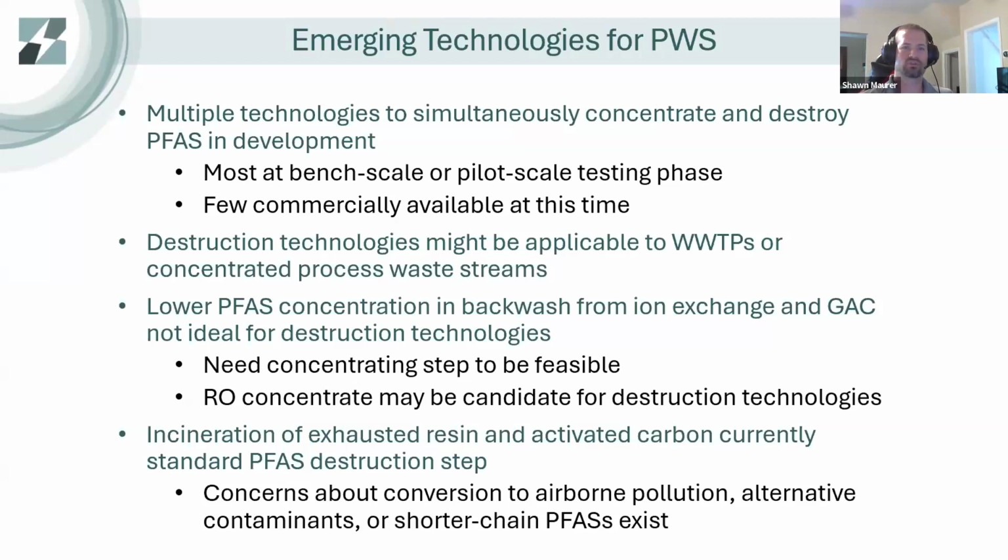Because it's more economical to destroy concentrated PFAS, it may be more economical to deploy these kind of technologies at the wastewater treatment plant rather than at the water treatment plant, especially since wastewater from the water treatment gets discharged to the wastewater plant anyway. But if PFAS buildup in sludge that's being land applied might be a concern, then maybe there's an agreement with your local wastewater plant that the on-site destruction of PFAS at the water treatment plant might make more sense.